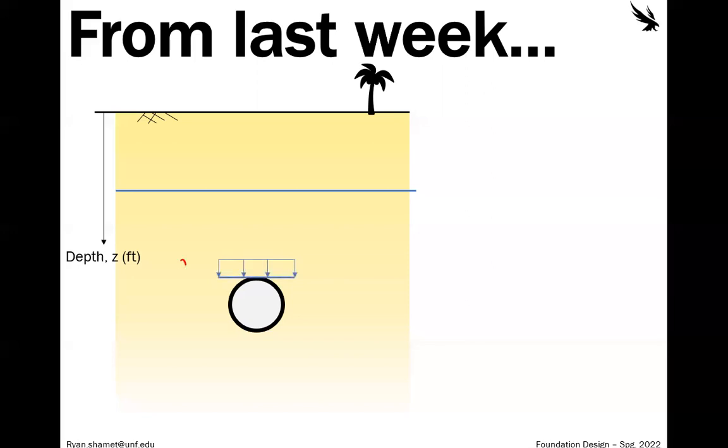And remember, we show stress as a sigma, a lowercase s. And those in situ stresses are important. So that's what we're calling this, the in situ stress. And that just means in the natural state or in its natural condition. So understanding how those stresses are based off of the soil above it is super critical in geotechnical engineering for designing structures, but also for understanding geologic formations as well.